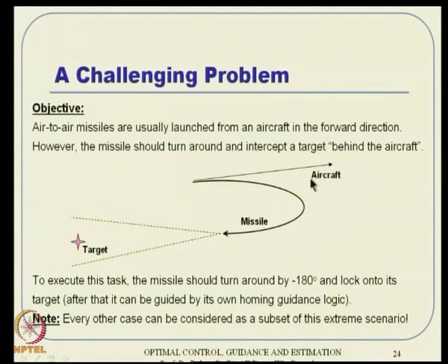If you increase the angle of attack, the lift is increased, so the aircraft goes up, and the attitude also goes a little bit higher, and then the drag is also more. So, it reduces the speed and comes back, and then you decrease the angle of attack, and then you are behind the target, and then you will be able to fire it.